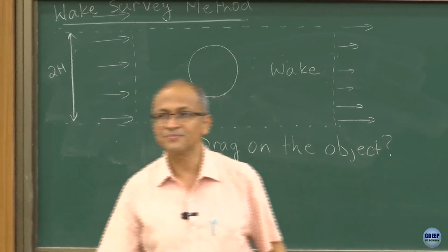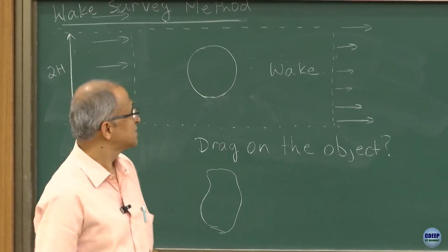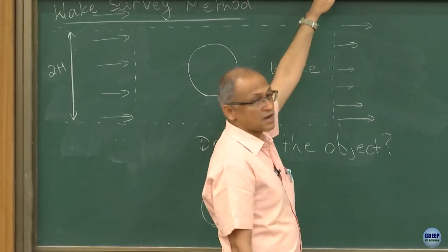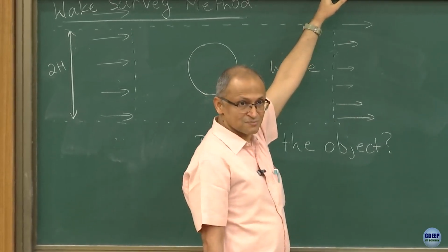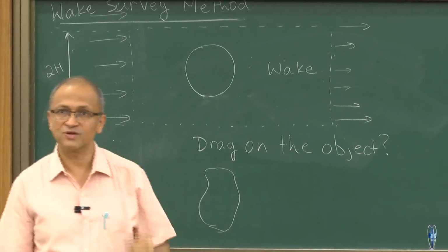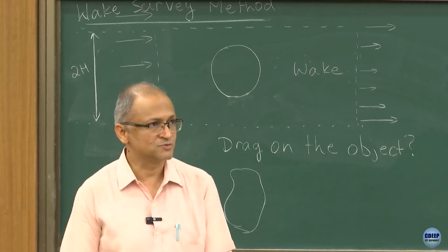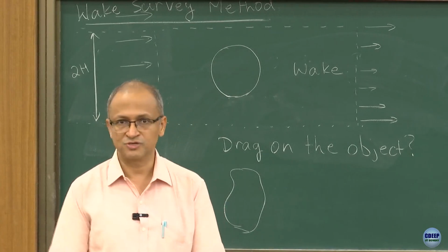So, that's what we sort of understand. It may appear as if we will have to use our momentum conservation equation, but one simple rule that we have to understand is that before you apply the momentum conservation equation, always apply the mass conservation equation.